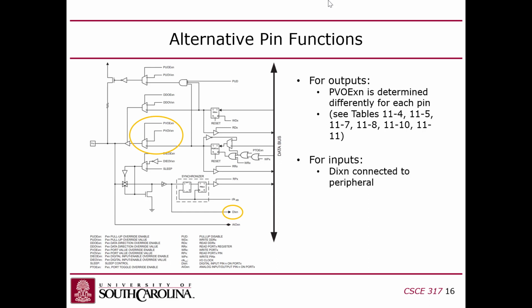So I was kind of freaked out by this when I first started looking at this. I was like, I'm going to have to go in and write this big initialization section to configure all the pins before my code runs. That's going to be a pain. But it turned out I never had to do that, because if you use them as GPIO, they just work as GPIO. And if you use them for their other purpose, like if you tell them to do an SPI transaction, they'll just automatically and transparently switch over to that function, which is kind of cool. I didn't believe it till I actually tried it.